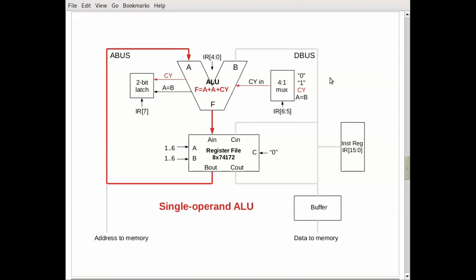And if you think about that, that's a left shift and bringing in what the Z80, I think, used to call the left shift through carry. I may be misremembering that, or excuse me, rotate through carry. But this shifts the ALU one place to the left and then brings whatever the carry is into the lowest bit.